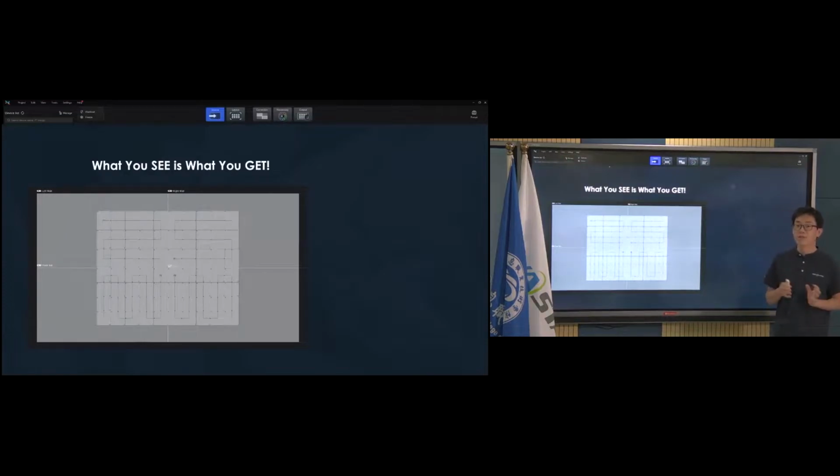The first thing we need to do is to set up a proper source for our LED display. But in the past, with the Nova LCT platform, you had to calculate the coordinates of the video source input position in front of the screen, then check whether the video source fits the LED display size correctly.